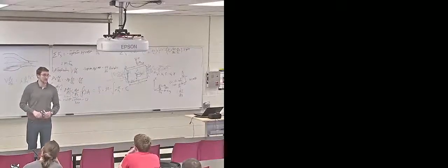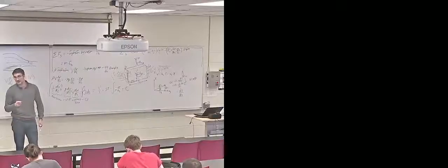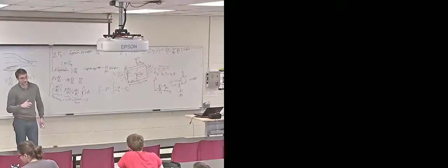What we're going to do right now is make the assumption that the fluids we're working with are incompressible. And this is a pretty good assumption for most cases. As a rule of thumb, if the speed of the fluid is less than about 0.4 times the speed of sound in that fluid, then an incompressibility assumption is relatively good.